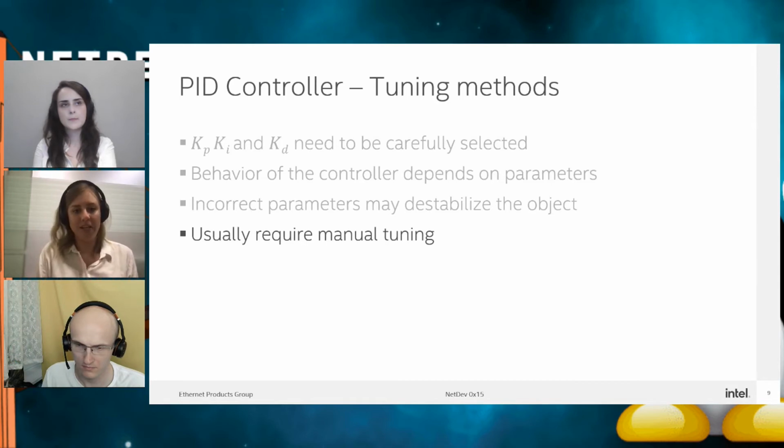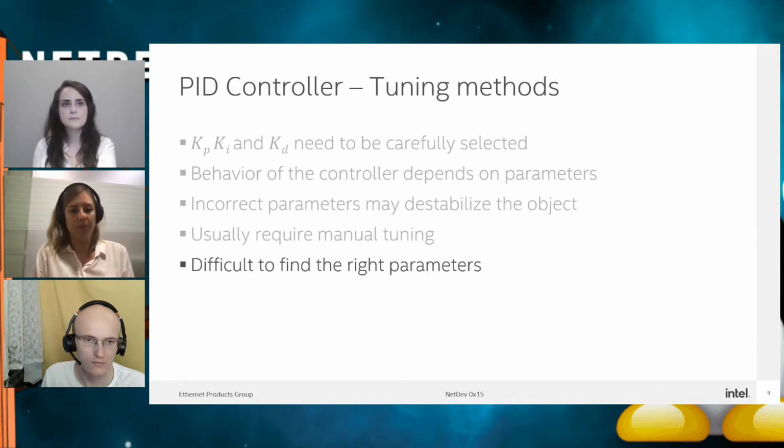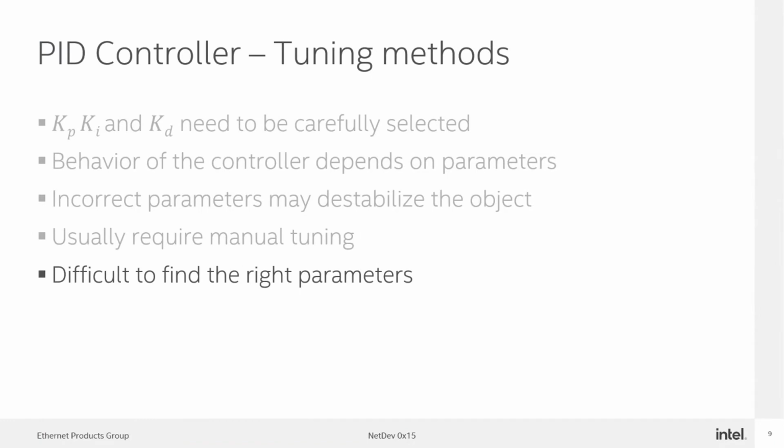Besides that, nowadays we have many possible tuning rules. There is a handbook of PI and PID controller tuning rules that presents over 560 tuning rules defined only for PI controllers. But the problem is that the most classical methods require explicit mathematical modeling of the whole process plant. That is, first of all, expensive, as we have to calculate the transfer function that represents the process. And the transfer function itself can change over the hardware lifespan, so the whole process has to be repeated.